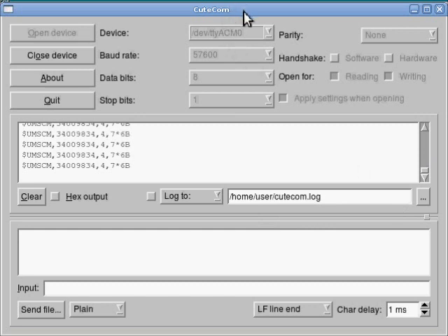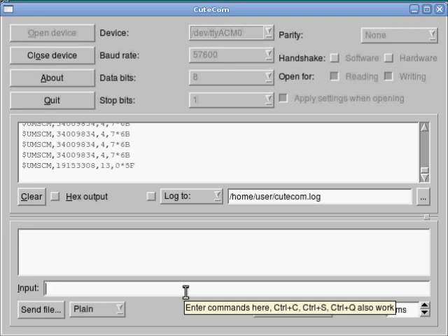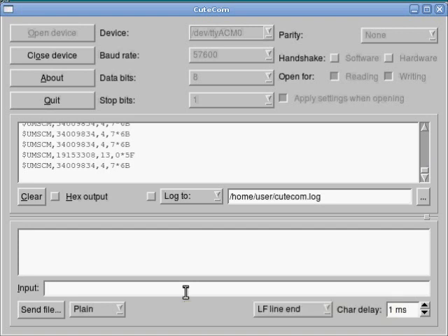Okay, so we're connected. Now I'd like to show some basic commands that the receiver understands and how it responds to them and what effect it has on the configuration of the device. So the first thing I'd like to show is changing the output from basic output, which we're seeing here, to full output. So I will type full on. You can see that we received a MSG message back, which basically just is a bit of text saying OK. It acknowledges that it received the command.